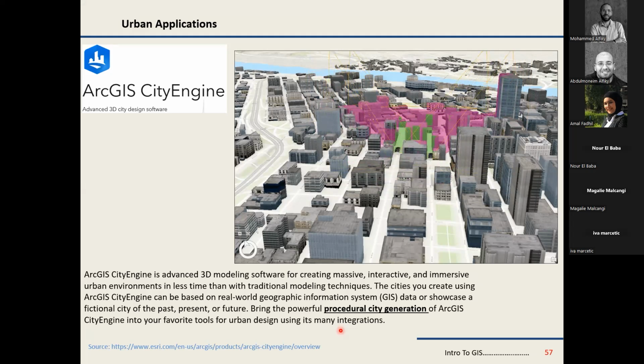And the City Engine license basically allows us to build the city using what we call procedural city generation. Basically, we set the rules by which the city should be built, by which the roads should be laid out on the land, and the parcels: the minimum size of the parcels, the maximum size of parcels, the proportions of its dimensions.